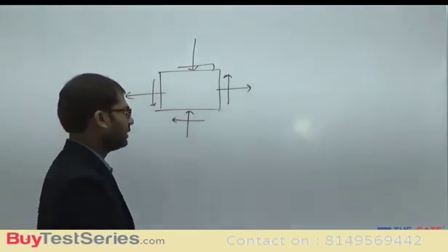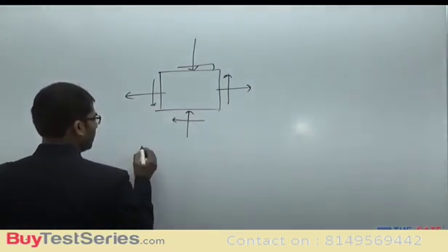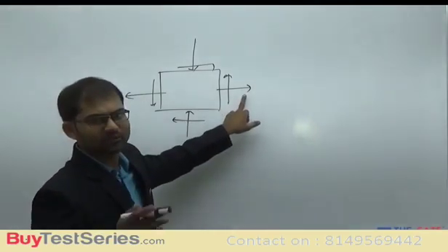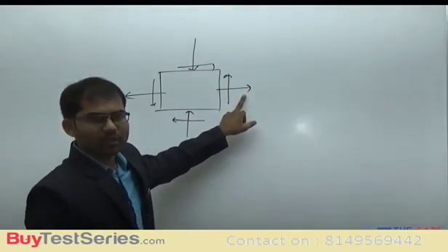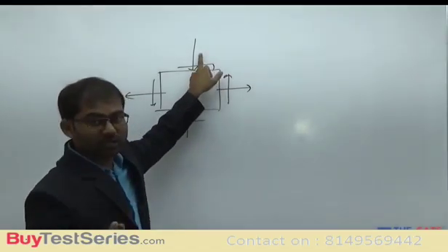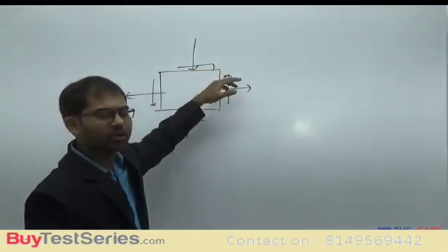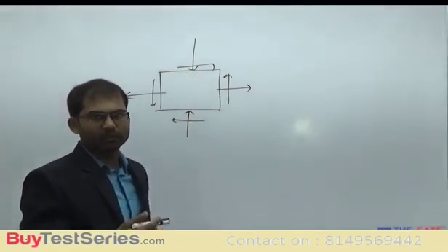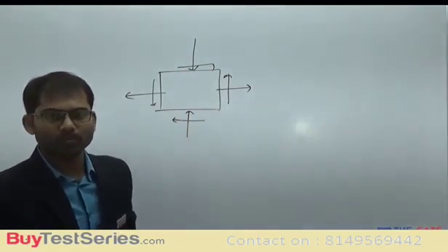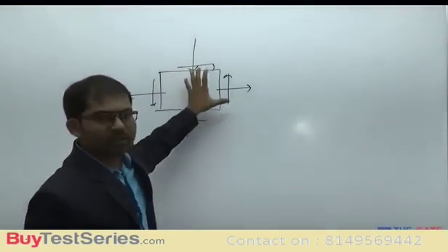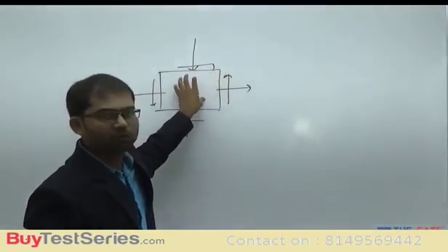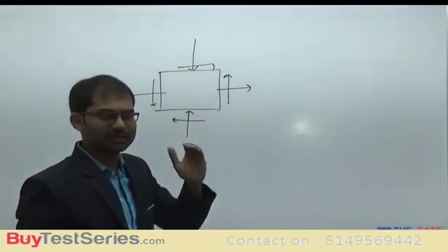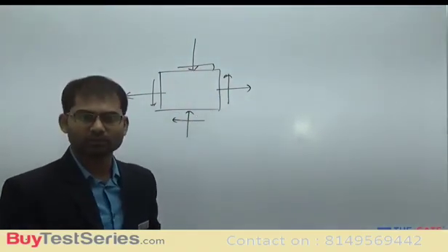Generally, you think that if the strength in tension is some value and this tensile loading is less than that value, failure will not actually occur by tension. If compression loading is more than the compression strength, it will fail by compression. We can't take individual values. Generally, our mind will tend to think in that way, but actually it's not true. Because when combination loading cases are there, the way the metal is going to fail depends upon the effect of all these loads. So we can't decide simply by taking strength in only one type of loading case.